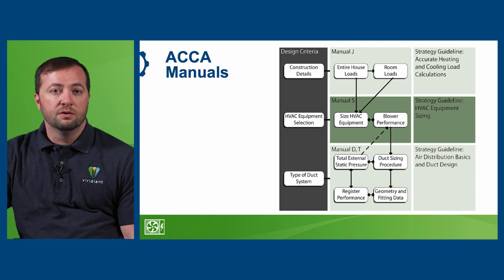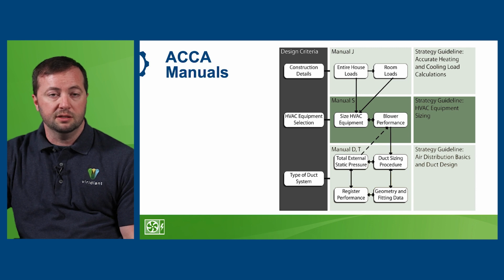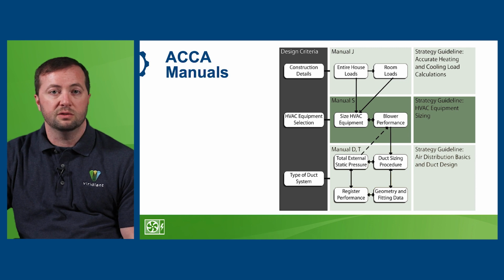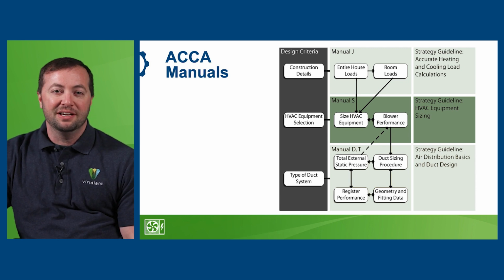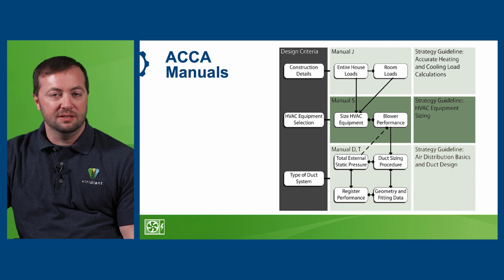off. For heat pumps that will be installed without auxiliary heat or other backup heating systems, you'll also need to consider sizing for both cooling and heating. Typically, we size for cooling. With those specific system types, you also want to take into account the heating needs. Please don't make the classic mistake of installing oversized equipment. It's the pathway to poor performance and high cost.